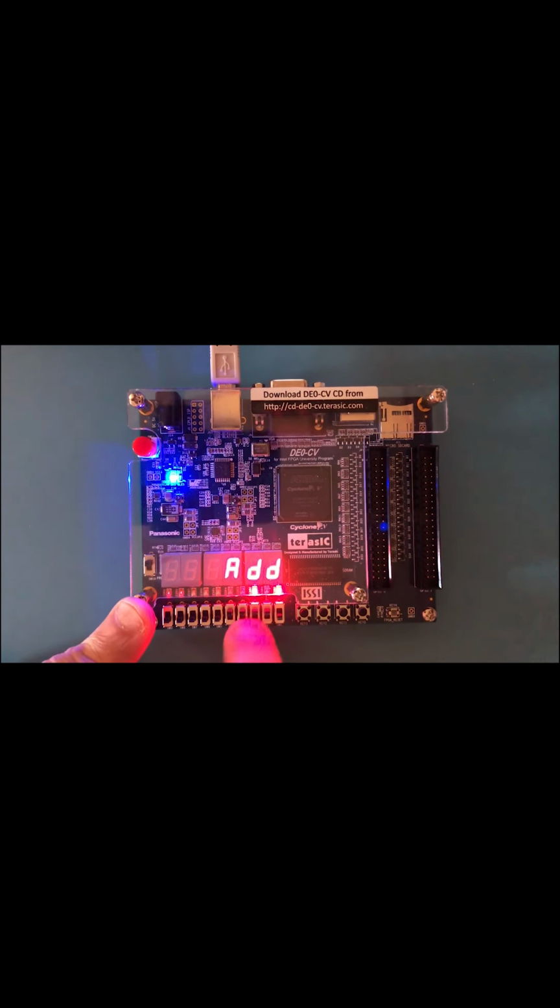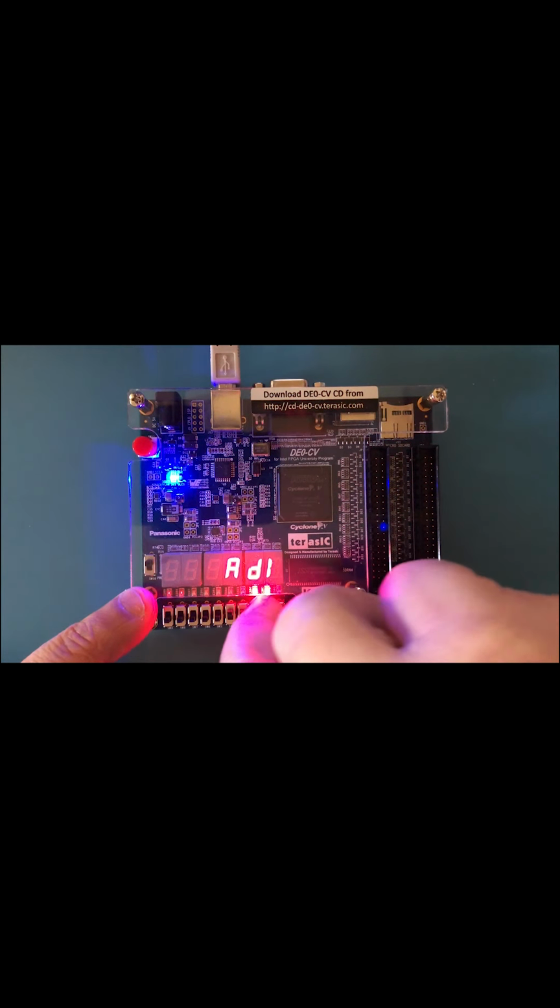It went to instruction 5, which is an add. Let's go back. I know it's going to cycle because 8 is an increment, and it's going to go to 9, then jump back to 4, and then go again: 5, 6, 7, 8, hit 9, and jump back. It's going to do it many times. Here we have ADI, and this is what we have in the ALU. Let's advance it a little bit more and then stop here, because at least two thirds of the program goes into this loop.